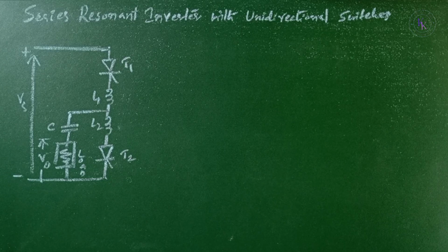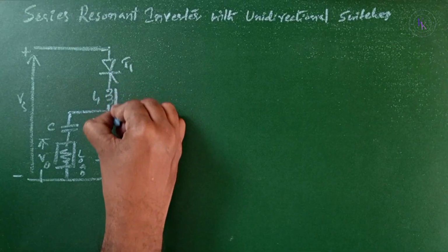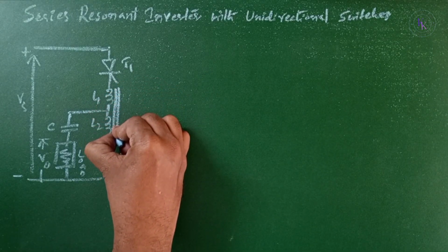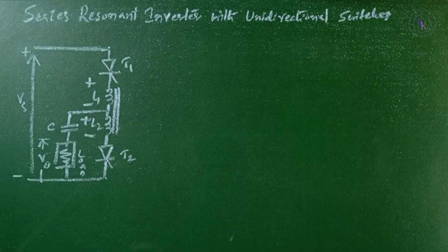This is a simple circuit for a resonant inverter. However, the power flow from the DC supply is discontinuous. The DC supply will have a high peak current and would contain harmonics. An improvement of the basic inverter can be made if the inductors are closely coupled as shown here. When T1 is fired, the current through T1 begins to rise.